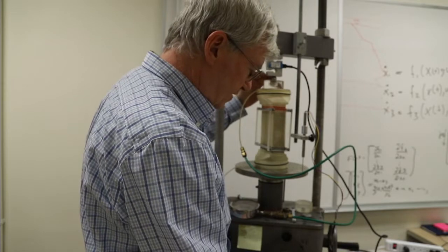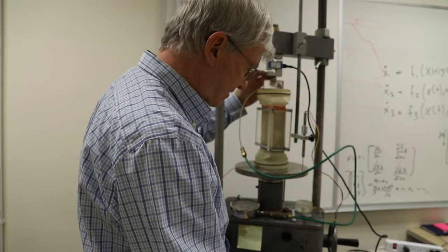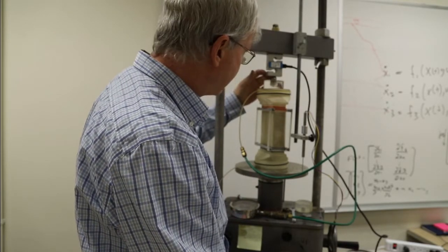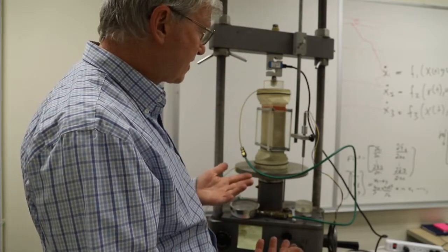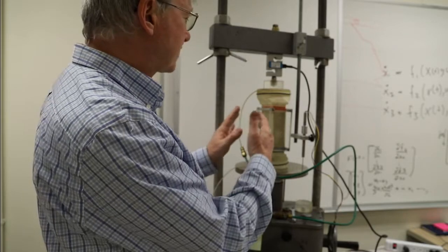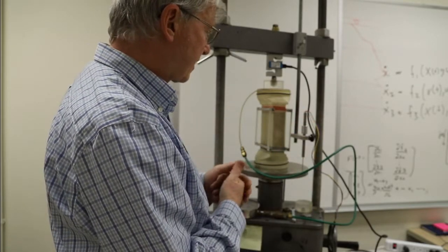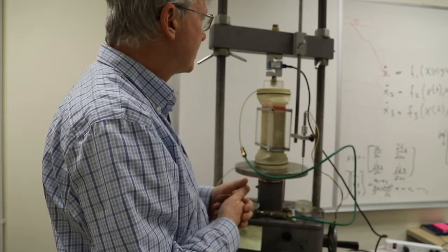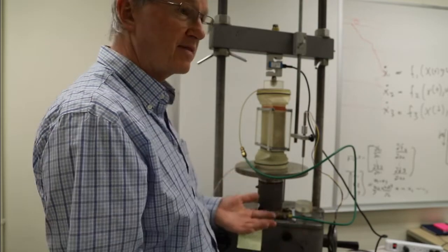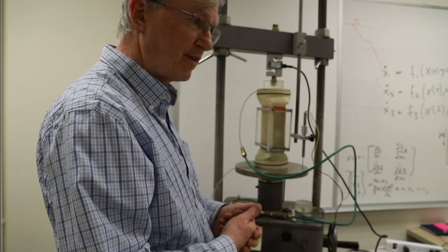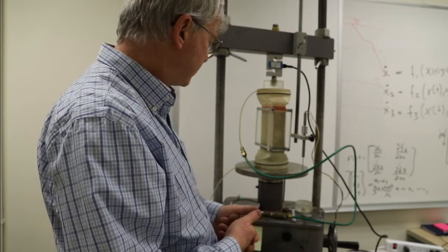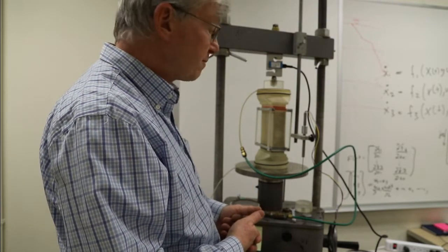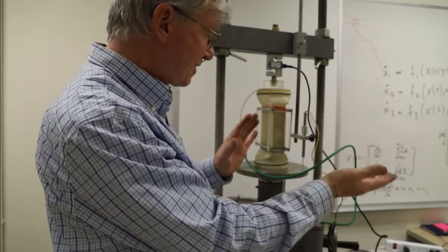So think about what you're going to expect from a dense sand in plane strain. What sort of mode of deformation? Now we know it's plane strain, so the bulging is only going to happen again to the left and to the right, but do we think it's going to be a generalized bulging failure or a discrete failure plane with localization or something in between? Hopefully it's not going to be tipping because it's not centered.